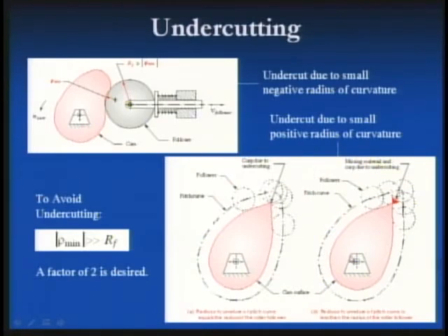So here's a depiction of what we're talking about. Instantaneous radius of curvature of the cam varies as I travel around the cam. While I want to dwell, it will be constant at the radius of the cam, but where the cam shape is changing, the radius of curvature is changing continuously. I want to avoid either of two situations. The first one is quite easy to visualize, so I'll look at this first.